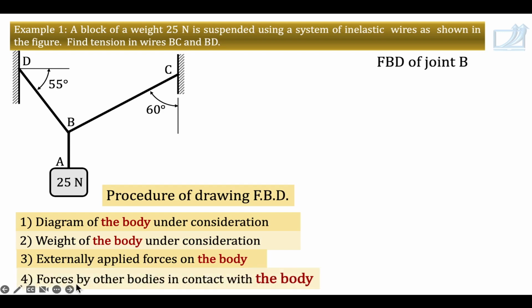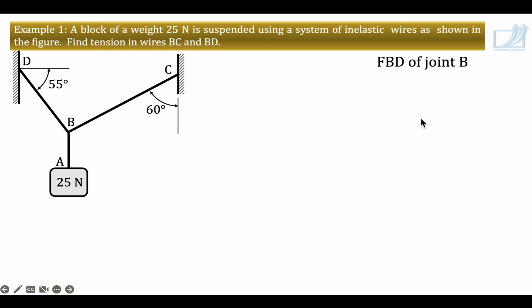And finally, forces by other bodies in contact with the body. So forces by other bodies which are in contact with the body under consideration. These are actually reactions. So to show these forces by other bodies, nothing but reactions. Watch the video, link of the video is given here. Okay, so according to this procedure, let's complete the free body diagram.